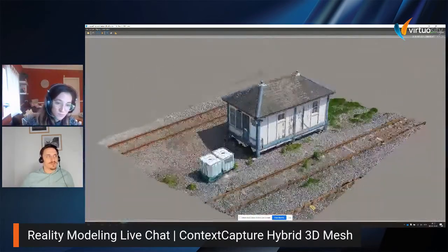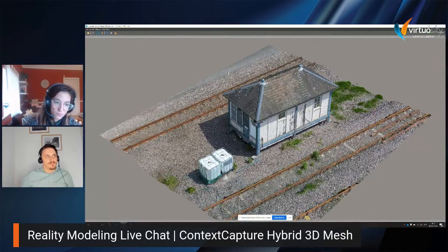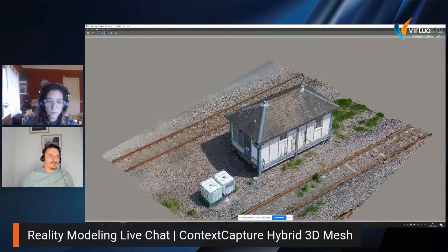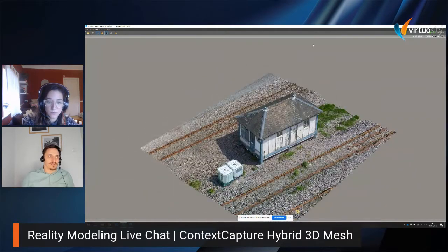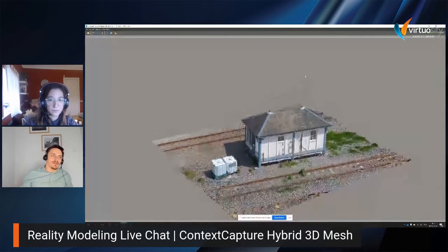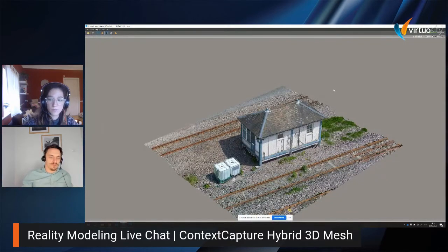Also, what is a good advantage of photos and drone imagery? Let's just imagine that we are scanning a bigger area, for example in winter. The day is rather short, and just imagine how long it takes to scan a big area. And the sun is also moving, so the colors are still changing. Terrestrial laser scanning especially is going to take rather a long time, going around some bigger area, and we can finish with a product which will have different lighting on each side, and it will not look natural.